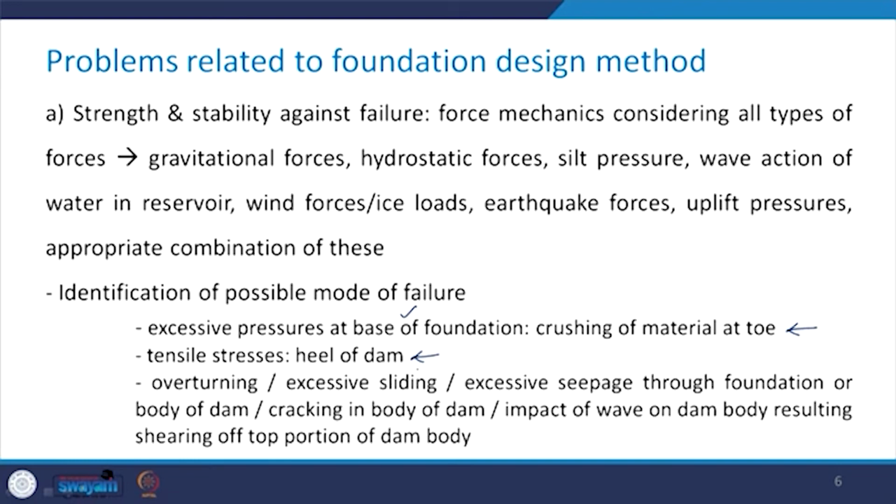There can be cracking in the body of the dam, and obviously the impact of the waves on the dam body would be there, and that can result in shearing of the top portion of the dam body. So, it is very important for us to identify these possible modes of failure while going for the foundation design of these dams.